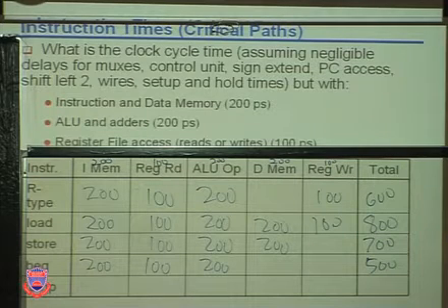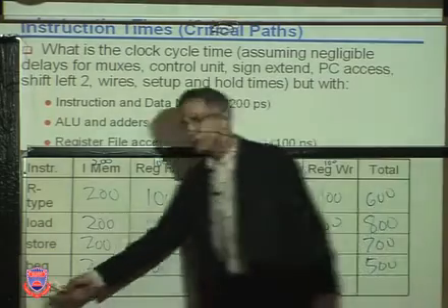Pardon? No, we don't write anything back to the register file on a BEQ. We don't change any data values in the register file on a BEQ. I'm sorry, we change the PC, but we do not change anything in the register file. Branches don't change data.